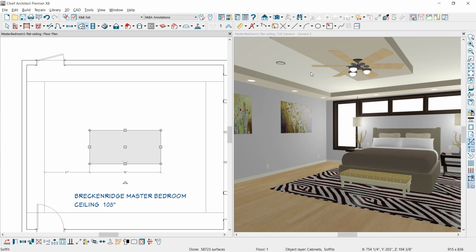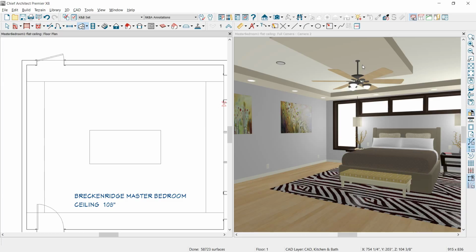Now sometimes you'll notice that my soffit, which is at the same elevation as the outer soffit that we placed against the walls, sometimes the electrical won't update until you rebuild the model. There's also a shortcut on your keyboard, F12, and it will move the electrical down. Now both of these soffits are approximately 4 1/8 inch below the ceiling, so there's a gap there, and that's where I'm going to stick the next layered soffit in here.